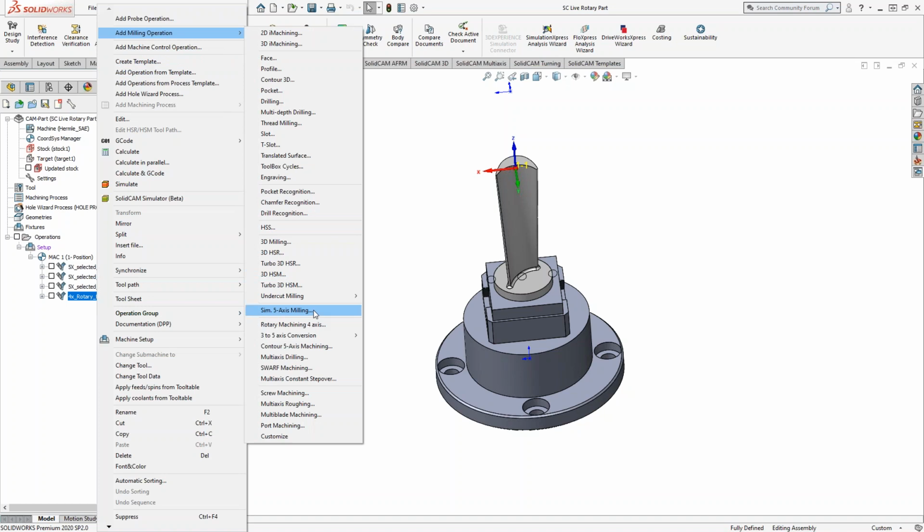This is the parent toolpath to pretty much all the other ones on the list here. And that's because inside this one toolpath, you have different options to angle the tool, to select geometries. There's lots of different things you can do in this one toolpath that pretty much once you align the parameters, you can do very similarly in these other ones. You can think of these other ones like the toolbox cycles, where a toolbox cycle does a specific thing like a slot or an additional slot pocket, like we did that one day with the slot, flat on a cylinder. All of those are a type of pocket or profile, but in the toolbox cycle, it's streamlined for that one application. So you can think of the same thing here. The simultaneous 5-axis toolpath can do all kinds of different 5-axis toolpaths and movements. These other ones streamline it to its specific example. So for instance, let's start with the first one here.